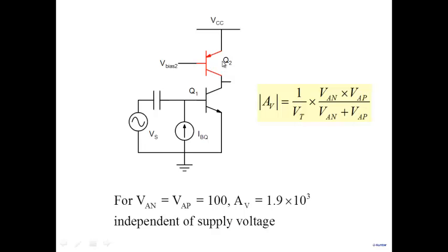And note the other thing. Remember, to get a high input resistance, what were you requiring? A low ICQ. Now, I can take these two transistors and bias them at low ICQ. Will it affect my gain? It won't affect my gain at all. Gain has no ICQ dependence. I can bias it at low ICQ and get high input resistance, and the gain is not affected. Gain is still the same.